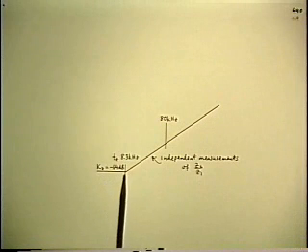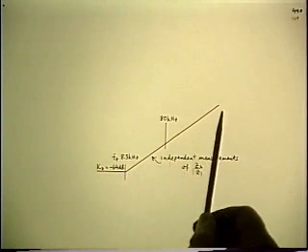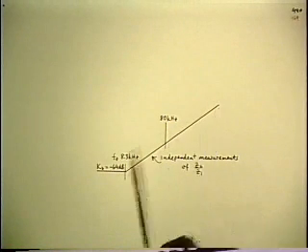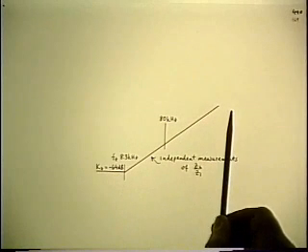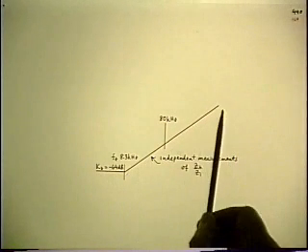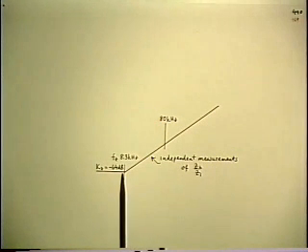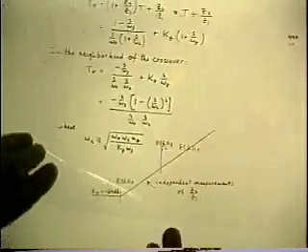I haven't actually noted it on this picture, but this is minus 64 dB down here, and that's at 8.3 kilohertz, and the highest measurement frequency was 600 kilohertz. So let's say it was 830, that would be a factor of 100. So by gain bandwidth trade-off, the magnitude at this point would be 100 times bigger than it was down here, which means I have to add 40 dB, so it's still minus 24 dB. So it's still much less than 1, even at the highest frequency.